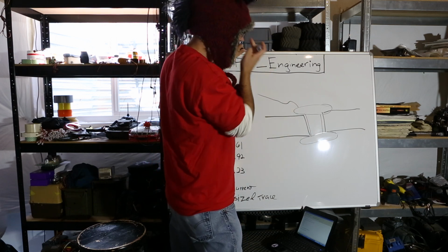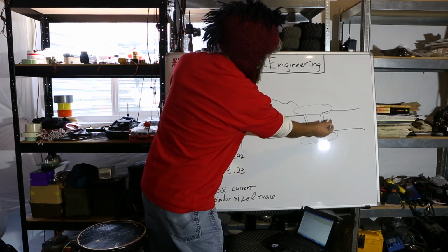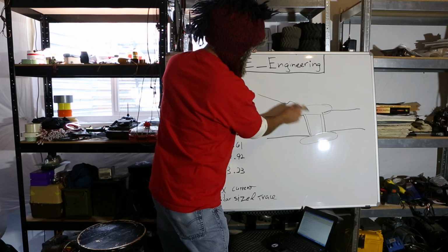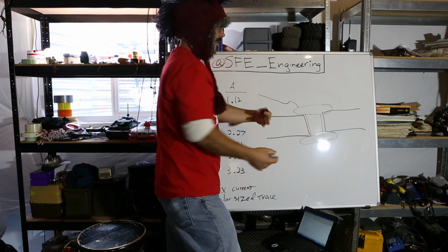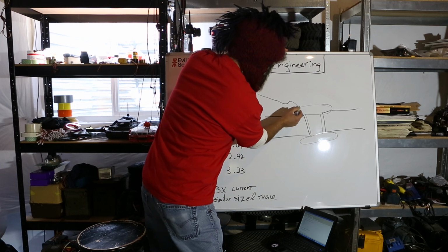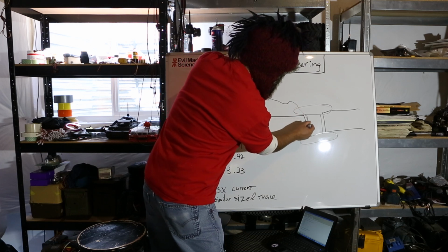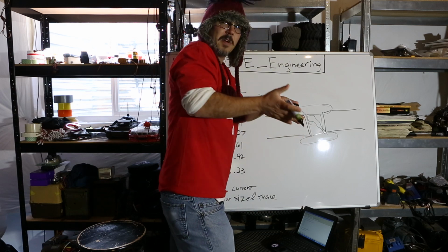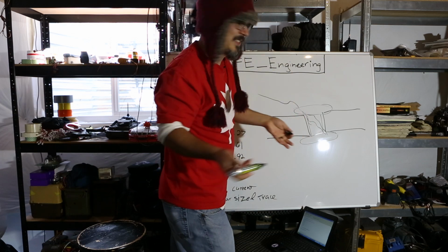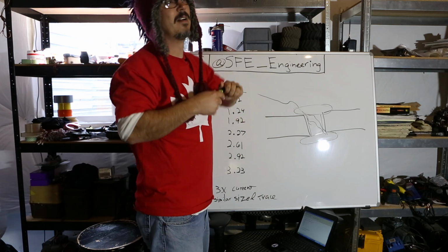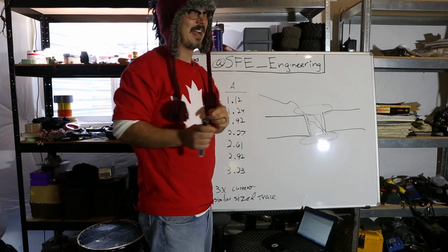I would worry more about parasitics that are generated in this shape, right? Because the current through this is going to choose the path of least resistance. So you'll probably get some current on the inside wall going like that, and on the other side too. And then you've got kind of a funky capacitor, maybe some inductance. But you know what? This never ends up being an issue for anyone that I've ever heard. But then I've never done any really high-speed design.